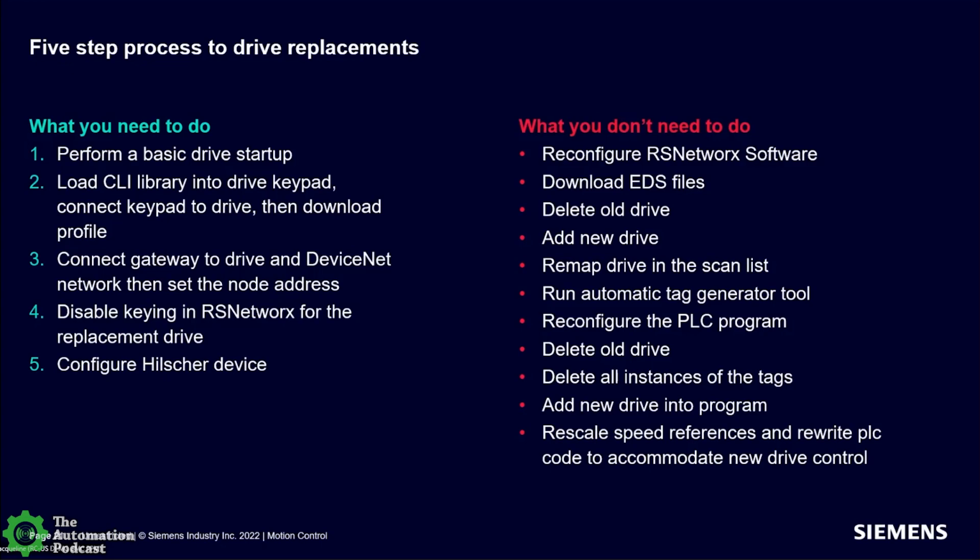It's just basic programming that you can do in a text file, like in a Notepad file, and then you just save it as a .cli file. Essentially what it allows you to do is program different drive parameters for SINAMICS, and then you just download it to the operator interface, and then you can take that to the drive, and that's how you would program the SINAMICS drive very easily.